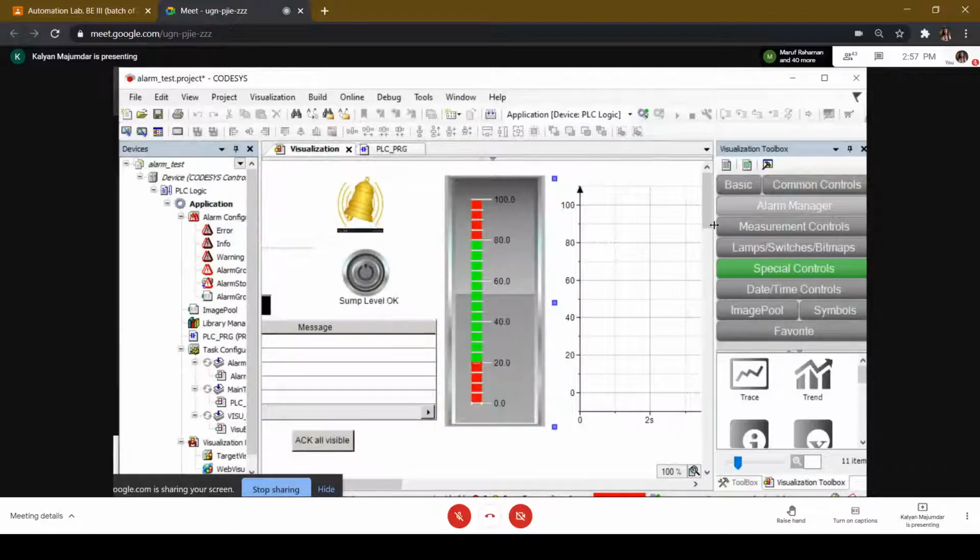So in our case, we'll be using this to highlight the fact that the level of liquid in the upper tank is either too high or too low, which is something abnormal. Right? You can also, of course, extend this. If the motor overload state is normal, you have one color. If the motor overload state is true, you have a different color, and so on. So you could do it for all variables, but then this is just an example for one variable.